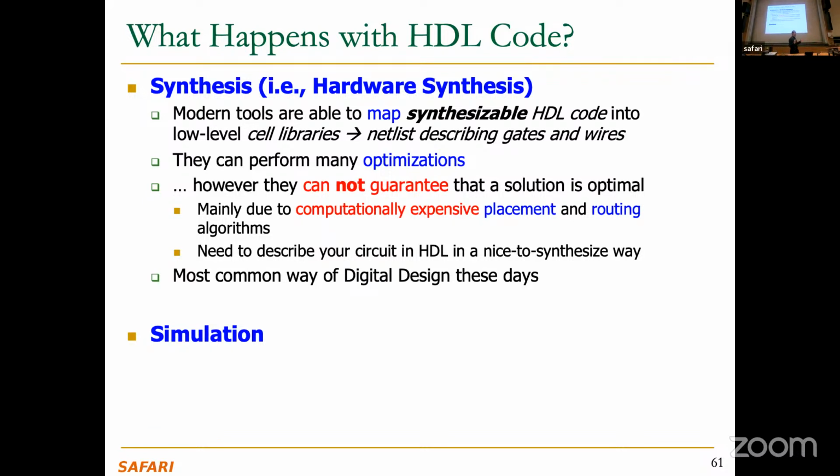There are some really timing critical paths of a circuit, for example, that the tool may not be able to meet the timing requirement for. You want to clock your processor at, I don't know, 30 gigahertz, right? At 30 gigahertz, you want this combinational logic to be so optimized that it fits that clock cycle. And you don't want to change your design to break that operation into multiple clock cycles. So hopefully the tool will meet that timing. If the tool cannot meet that timing, then you go hand optimize. If you're a really good designer, you may be able to meet that timing. If you're not a really good designer, the tool may be better than you, basically. But tools are actually very useful for very good designers as well.